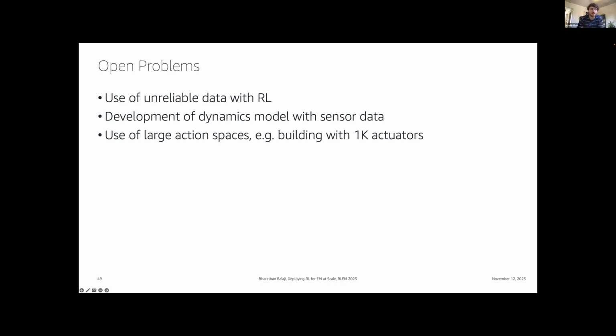Yeah, I guess the difficulty is also not just the scale of the number of zones that you're controlling at one time, but also the interactions between the zones physically that might have airflow between them. And so there are physical interactions between them, and there are physical interactions between the system level control and the local loop control. So if you're controlling many VAV boxes, then they can influence each other in terms of how the system level behaves. So that's a lot of dynamics to take into account for the reinforcement learning control. That's more of why I was curious.